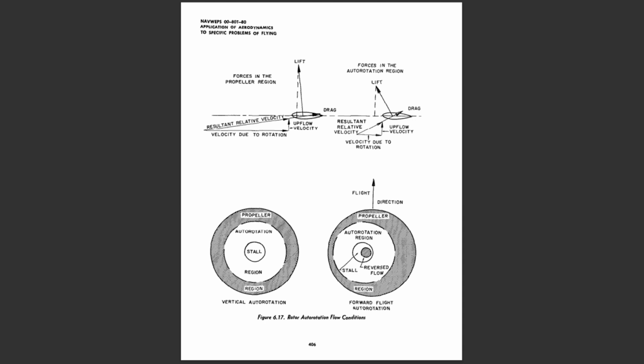First, consider a blade element near the tip of the blade as illustrated in Figure 6.17. At this point, there is a lift force acting perpendicular to the relative wind and a drag force acting parallel to the relative wind through the aerodynamic center. Since the rotation of the rotor is affected only by forces acting in the plane of rotation, the important forces are components of the lift and drag force in the plane of rotation. In this low angle of attack, high-speed tip section, the net in-plane force is a drag force which would tend to retard the rotor. Next, consider a blade section at about the half-span position, as illustrated in Figure 6.17.